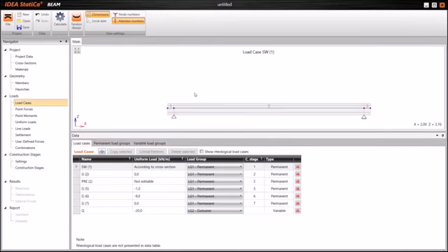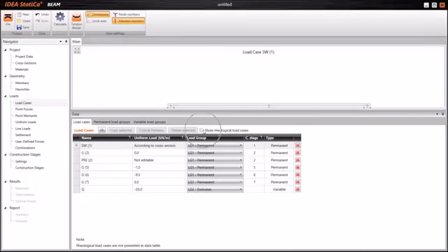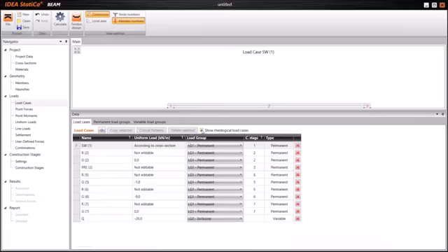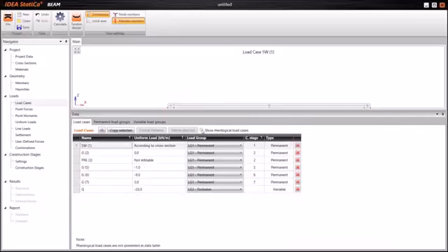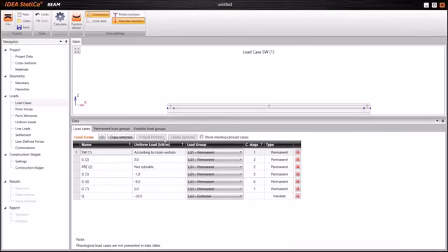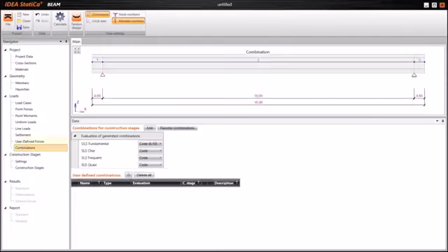Now we can go back to load cases just to explain why we didn't show these rheological load cases. You can press it on, and you see that we have also R, G, R, G for each construction stage. If you don't want to see those automatically generated load cases, you can switch it off. You can also explain better now the combinations, so that I will edit it.